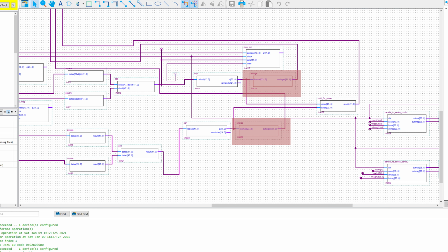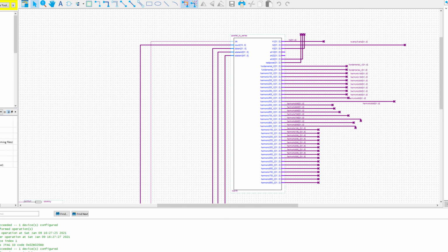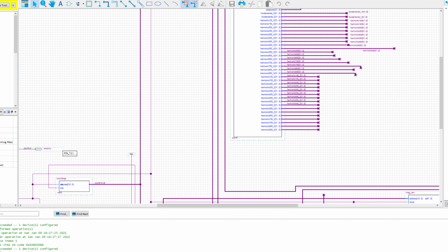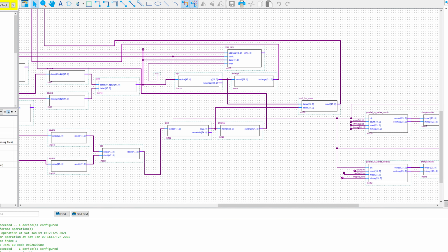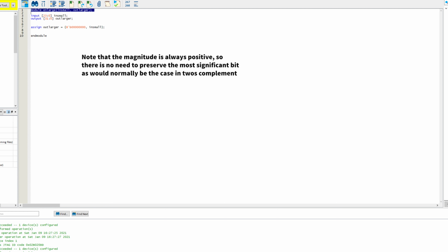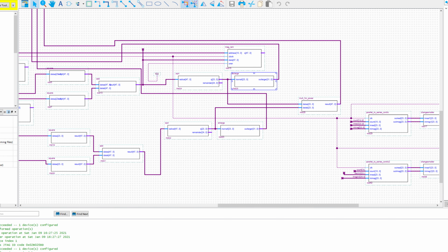The reason I've done this is just to make it easier to standardize the inputs into my embedded processor. So now I can keep all information going in at 32 bits. Now, just to give you a quick look at the code that's doing this, making it larger, it's just adding 8 zeros. So that works fine.